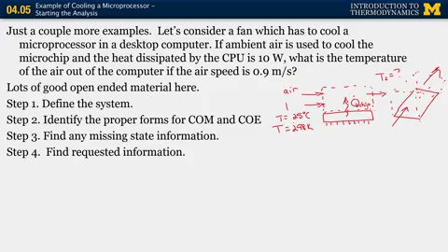And we're also given that the speed of the air into this de facto heat exchanger is 0.9 meters per second. If you have a box fan, a typical fan that you might pick up at a hardware store, that's on the low end of a box fan. So you're talking about a typical, not industrial grade, fan speed. So you could probably increase the heat transfer by increasing the velocity of the air by maybe an order of magnitude, just using conventional fans.